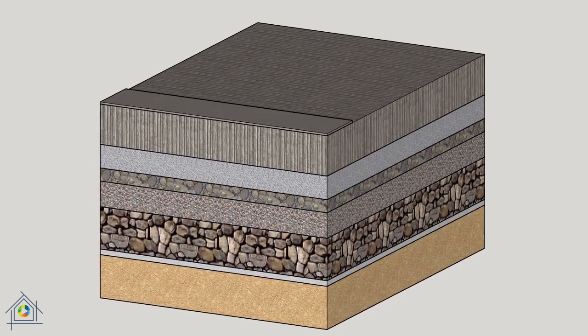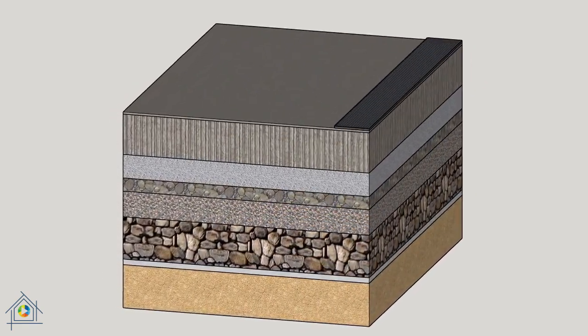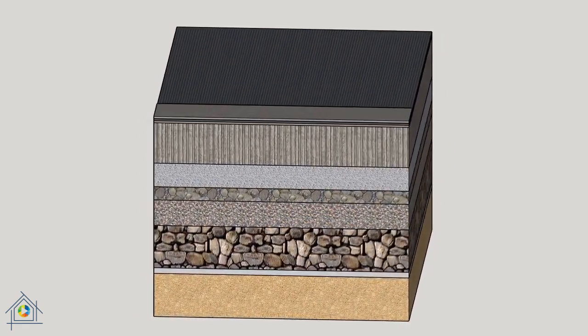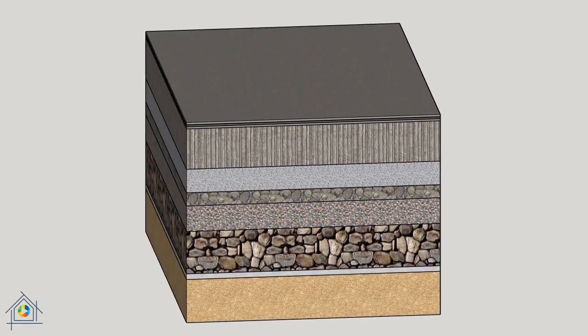The next layer is a moisture barrier that is applied between 2 layers of sand and cement mortar. The moisture barrier layer can be bitumen-based prefabricated moisture barrier. The sand that makes up the cement sand mortar must be fine so as not to damage the moisture barrier. The total of 2 layers of cement sand mortar, in addition to smoothing the surface, is a protection for the moisture barrier. The thickness of the moisture barrier and mortar is at least 4.5 cm.